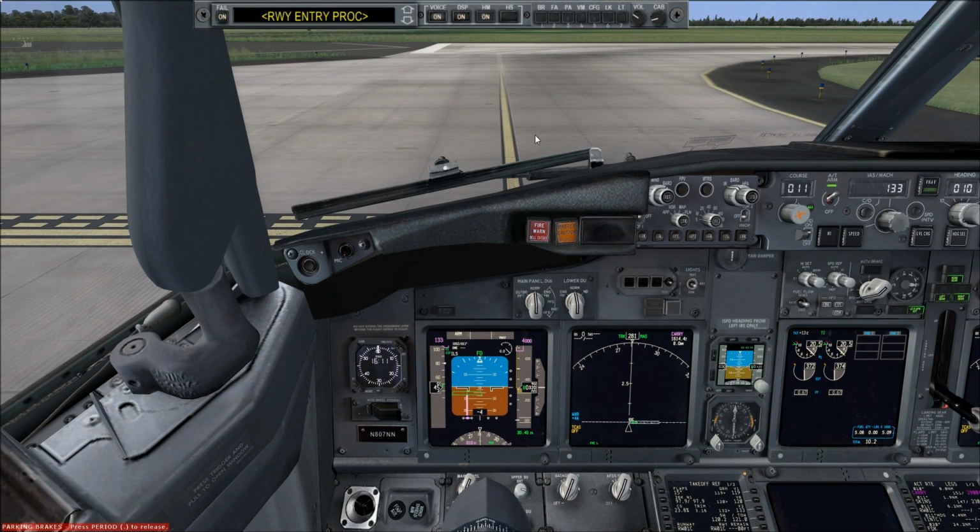I'm using FS2Crew, which I guess will help me out. It isn't designed for windshear. I don't think you can detect windshear, but hey, I'll use it to the extent that's possible. So what I'm going to do is taxi onto the runway, and once I'm lined up, I'm going to bring up Active Sky Next and create a windshear event using the debug option. What that does is it creates a windshear, a microburst, that's 3 miles directly in front of the aircraft.